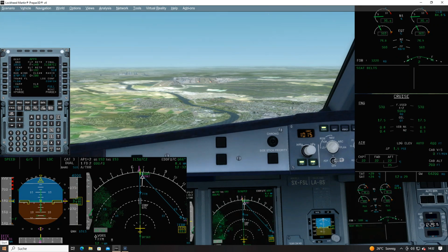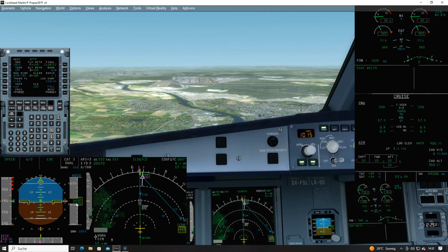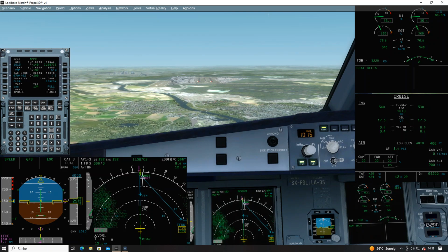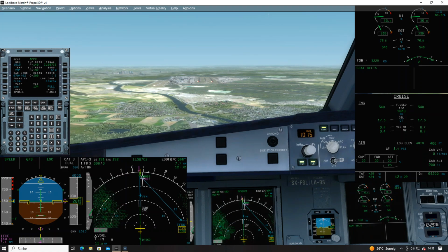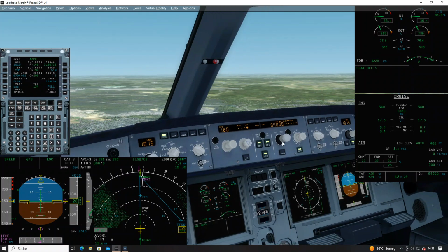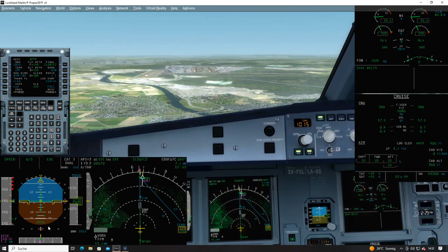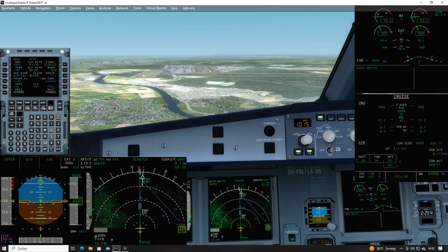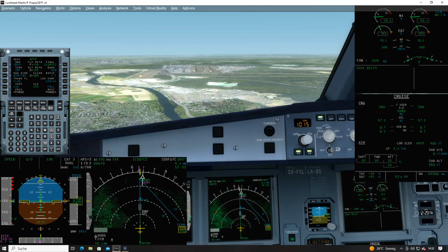We're at 3,200 feet, 100 feet now. Airport elevation is at 360 feet roughly. So 3,000 feet, a little less to go. For the go round, the altitude is 5,000 feet. I set 5,000 feet here just in case. 2,500 feet and downwards, the radio altimeter indication becomes alive. The radio altimeter is already operating all the time, also at higher altitudes, but passing 2,500 feet, the indication comes alive.